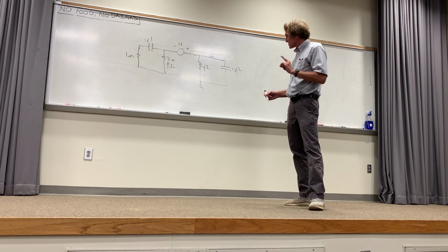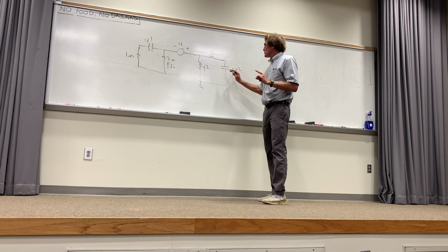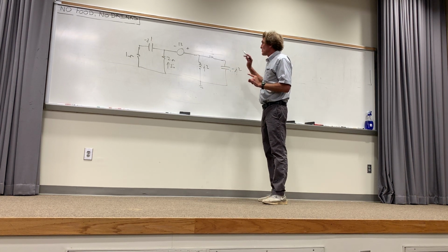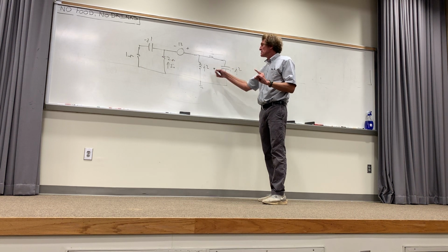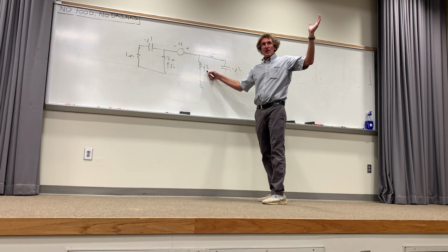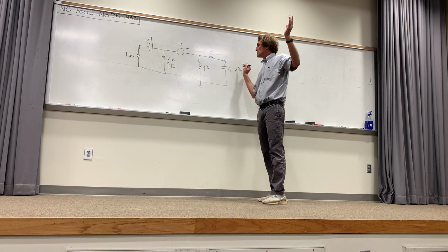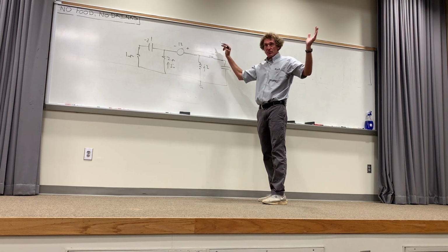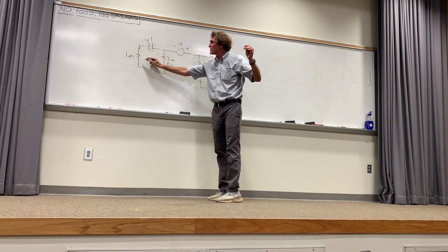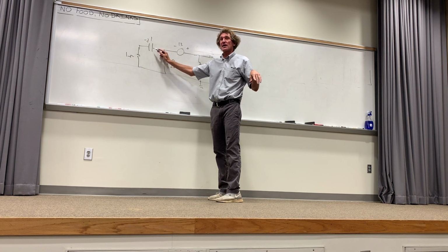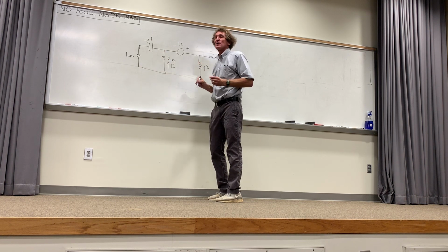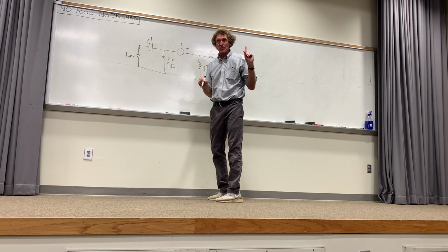Now let me discuss this. Can you see that the 2 and minus J2 are in series? One single impedance here would be 2 minus J2. That is in parallel with J2. Do you all see that? Therefore, you could take the parallel combination and get one single value. Now come down here. You see that these 2 are in series. Therefore, you could say the 1 minus J1 is in parallel with 2. You could get a single value for that.